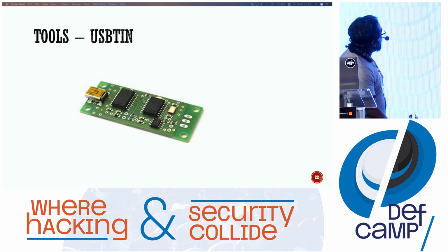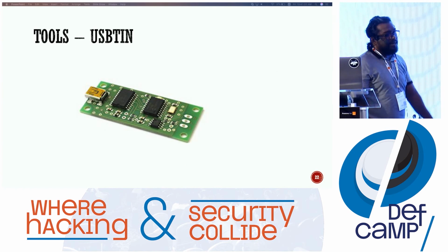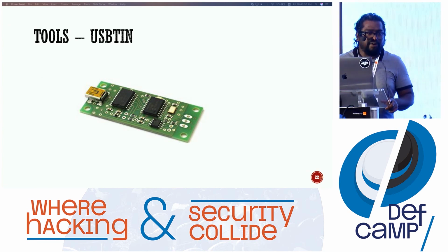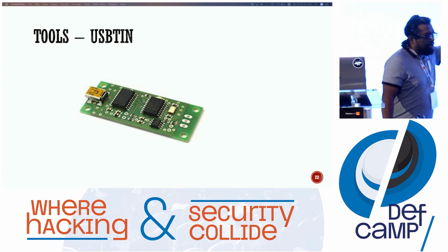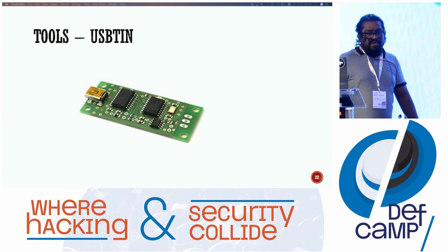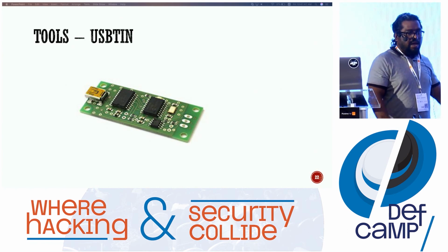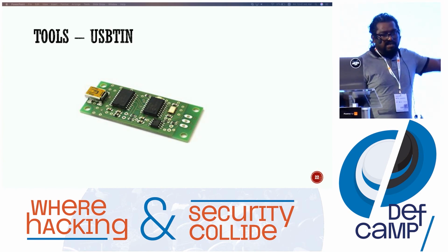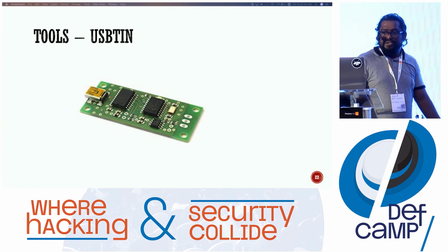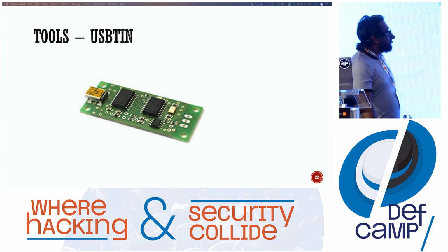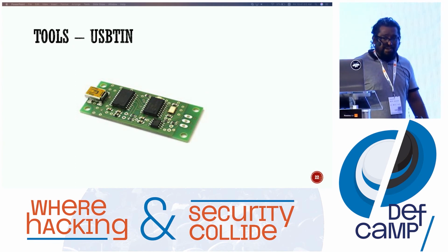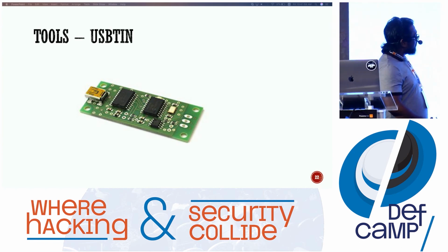There is an open source tool called USBtin. Here we are doing the car hacking village, so you can see these kinds of tools in the car hacking village, and you can see a live demo of how we can do some sort of CAN bus testing and how we can crack the seed keys or the ECU as well. USBtin supports only CAN bus messages, not the LIN protocol.